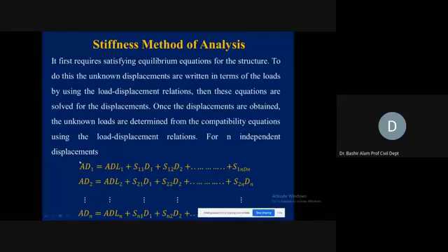DRS क्या था, it was the precondition at the support, displacement due to precondition at the support or at the redundant location था। यहाँ पे आपका क्या होगा, action corresponding to the displaceable joint। एक्शन को आप देखेंगे कि डिस्प्लेसेबल जॉइंट की जगह पे कोई प्री कंडीशन है कि नहीं, जहां पे एक्शन लगा हुआ है, वहां पे आप डिस्प्लेसमेंट को देख रहे थे करस्पॉन्डिंग टू द अननोन रिडंडेंट एक्शन। ADL1 is replacing the DRL now. तो ADL again आपका एक्शन होगा at the displaceable joint in the basic kinematic